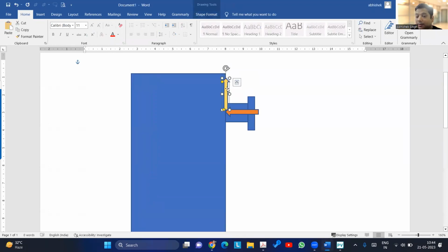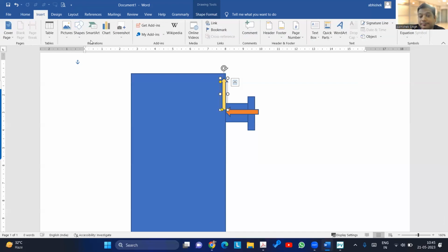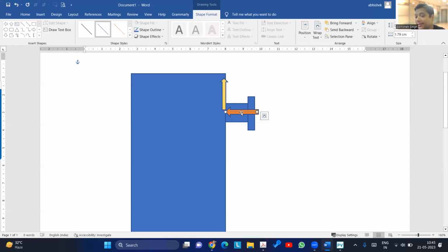Okay. So let us see, we are transferring this force from this face to the center line. Now, almost most of you have given that extra moment. Now, how will that moment come? For that, we need to know the distance, which is from the center line to the nozzle face. Let us say that distance is X, and the value of this load is FL.